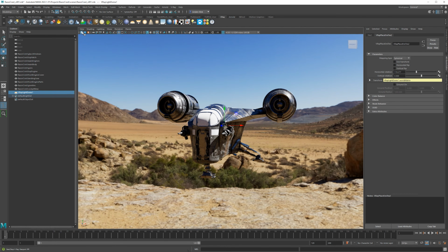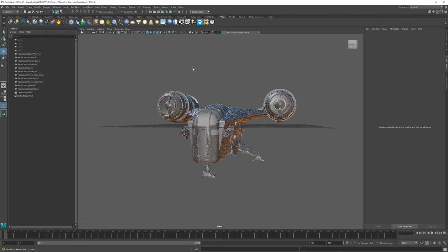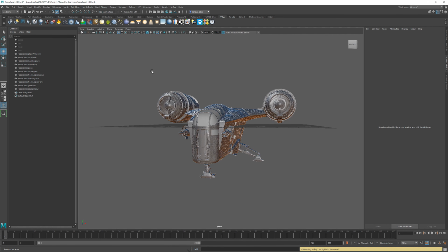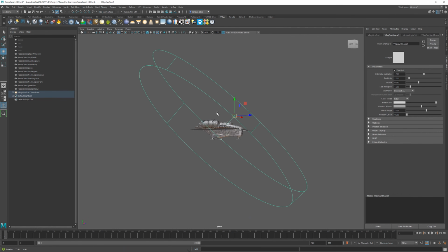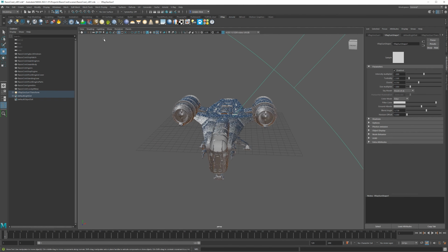Okay, right. So I'm going to turn this off, and then I'm just going to delete it. I don't care about that anymore. That can go. If I go back to V-Ray right here, you can see that everything is gone. There's no longer a default light anymore. It'll just say, hey, there's no lights, and it won't even give you anything. So it's just black. So next, I want to show you the sunlight. We can say V-Ray sun, create a sun, and this will give us a little sun right here. Cool. Turn this back on.